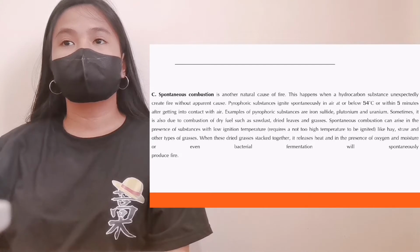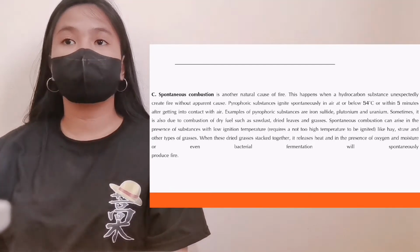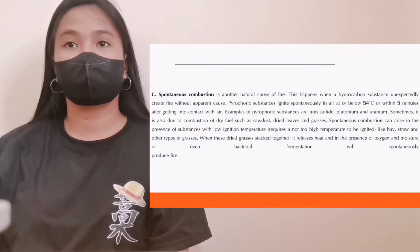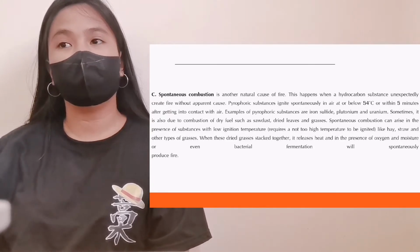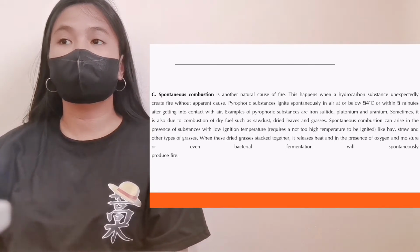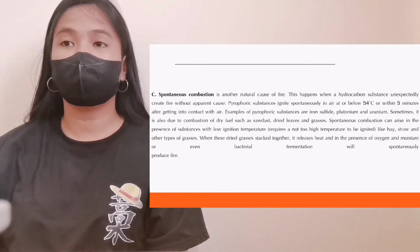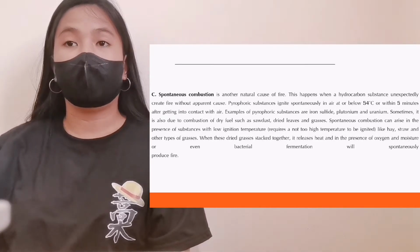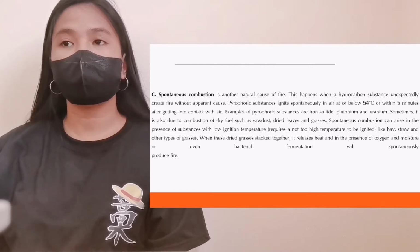Then next, the spontaneous combustion is another natural cause of fire. This happens when a hydrocarbon substance unexpectedly creates fire without a proven cause. Pyrophoric substances ignite spontaneously in air at or below 50 degrees Celsius or within 5 minutes after getting into contact with air. Examples of pyrophoric substances are iron sulfide, plutonium, and uranium.